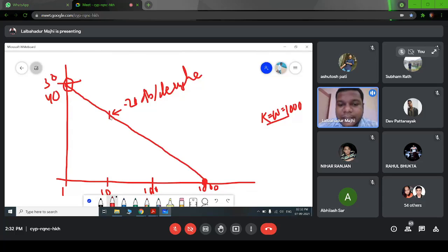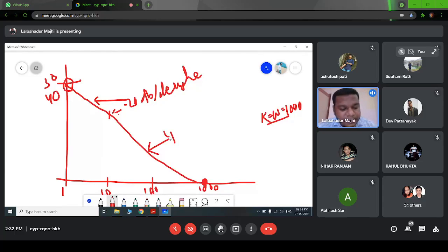So up to the next corner frequency 1000. Just let me erase it. So this is our first corner frequency, and this is our 20 dB per decade slope. From this we have to draw a minus 40 dB per decade slope up to 1000, the next corner frequency. We have to write the slopes.